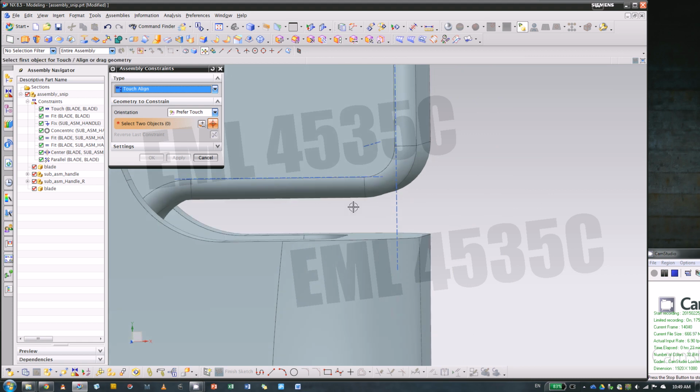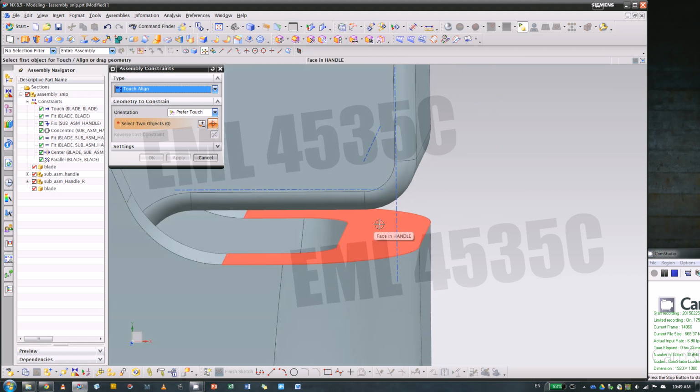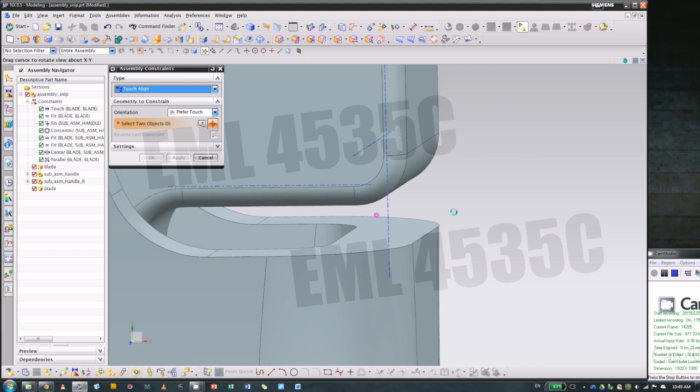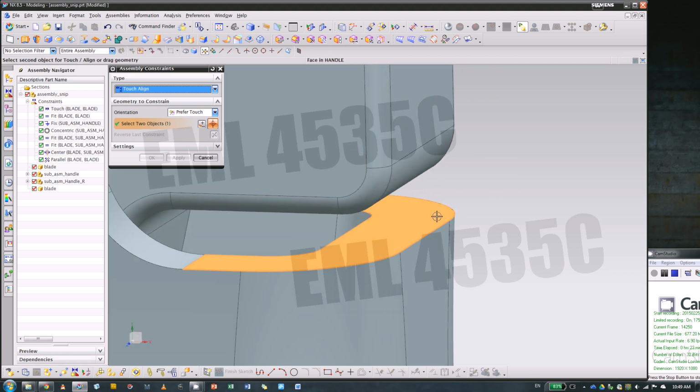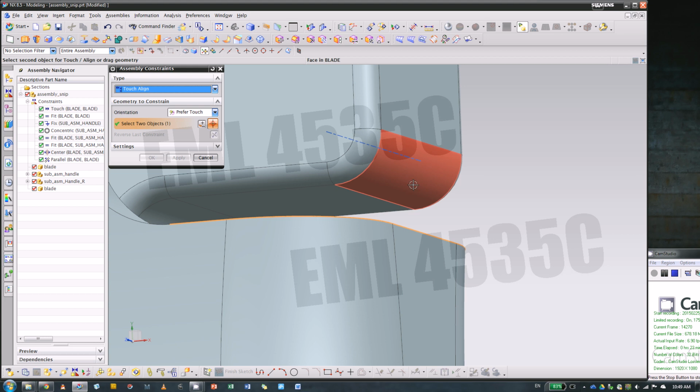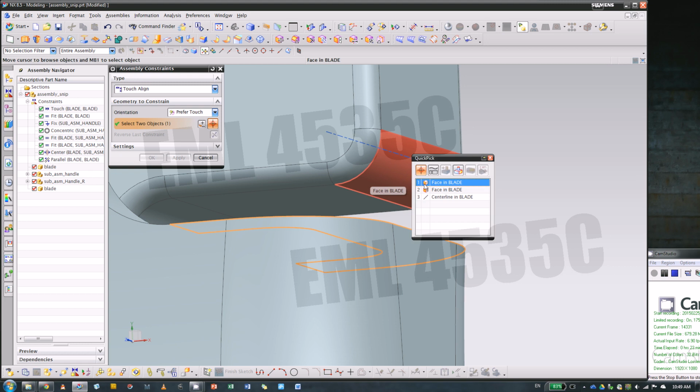because in NX it thinks this flat surface is an infinite face. Okay, you won't touch two infinite faces. As long as one of the faces is not parallel to the other one, they touch. So it doesn't really make sense to touch two parallel or flat faces. However, you can touch this flat surface to a cylindrical face. It's like you put a tire on top of the ground. It actually works.